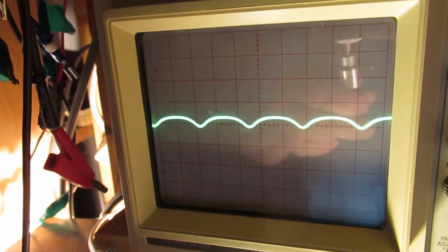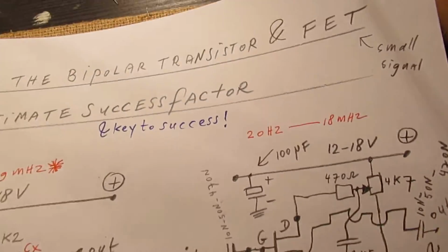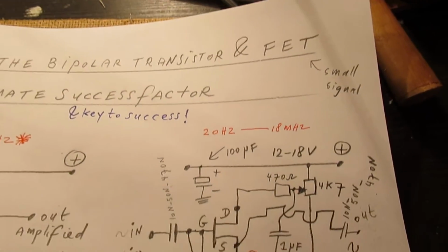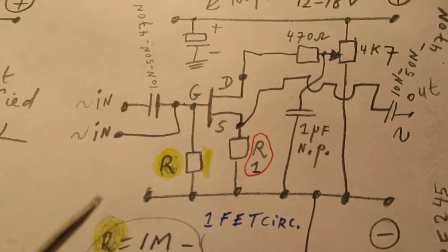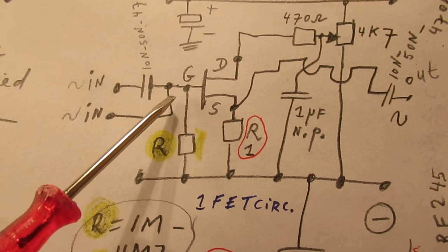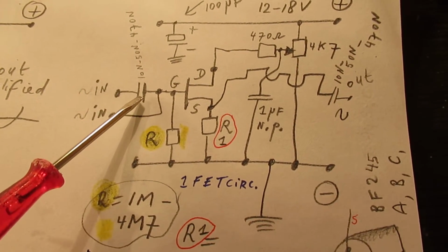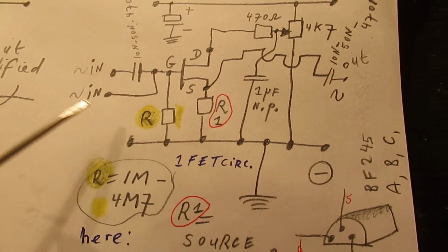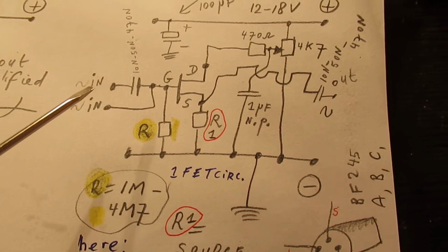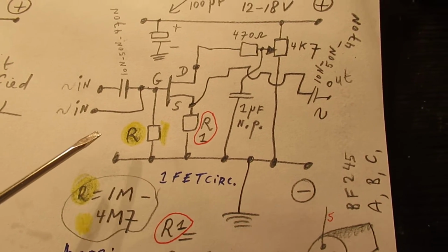And with this circuit that I publish now, there is in fact not so much amplification, but the good thing of it all is that it is an impedance transformer. So here we can connect directly to the gate or via a capacitor of, say, 300 picofarad, a tank circuit, an antenna coil, with a variable capacitor to tune in on radio stations.